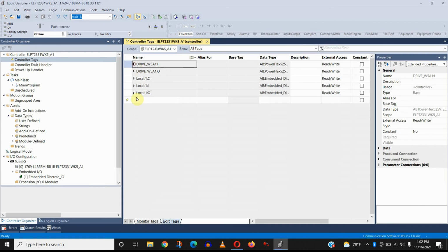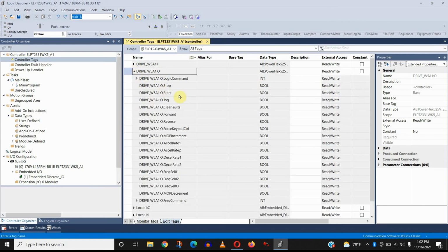Okay. If I look at the output tag listing, output meaning these are outputs from the PLC to the drive. These are actually the control bits: stop, start, jog, forward, reverse, acceleration, select acceleration rate 1, 2. So these are just control bits, right? Command frequency is the speed, the frequency that you'd like the drive to operate at. It's times 100. So 60 is 6,000. So far, so good.